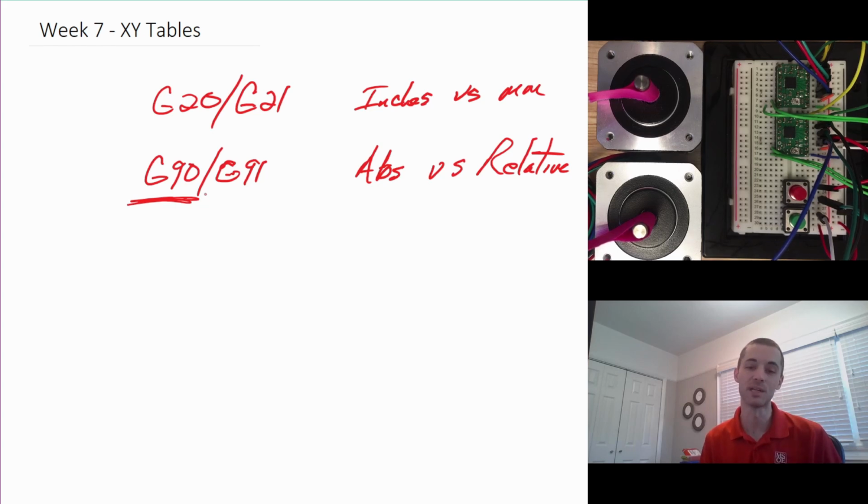Or if you wanted to ream and then hone, which is essentially trying to provide a certain surface finish on it. There are different ones that you can use. You can even modify them. There are additional macros that you can set up on a lot of machines where you have a set of 20 G code commands that you want to compact down into one because you're calling it so frequently.